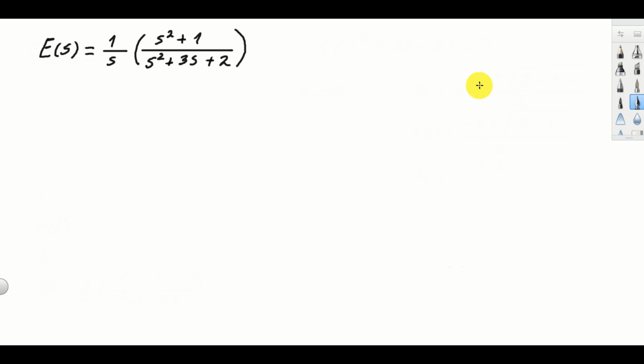The next question is, can we apply the final value theorem to this example? To investigate that, we need to compute the poles. So what are the poles of this function? The poles are the zeros of this polynomial in the denominator. The polynomial is s multiplying s squared plus 3s plus 2. And this should be equal to 0. Obviously, the first pole s1 is equal to 0. And we have two additional poles.